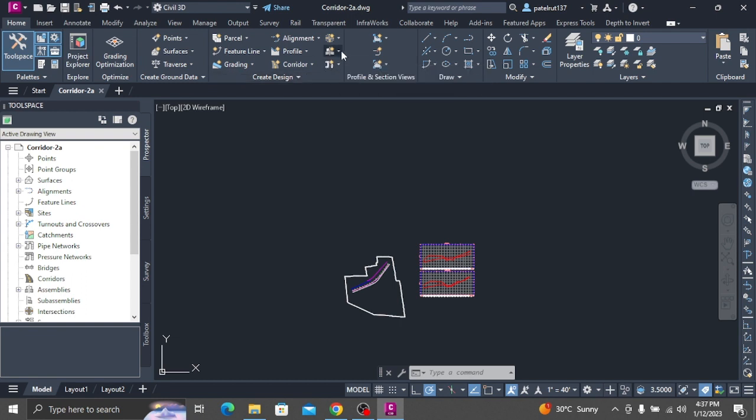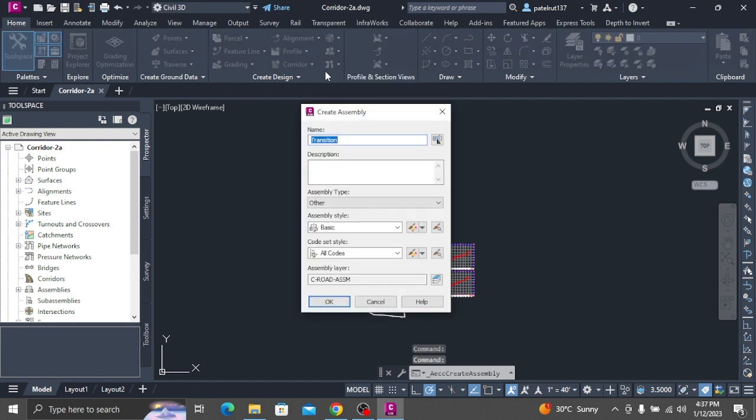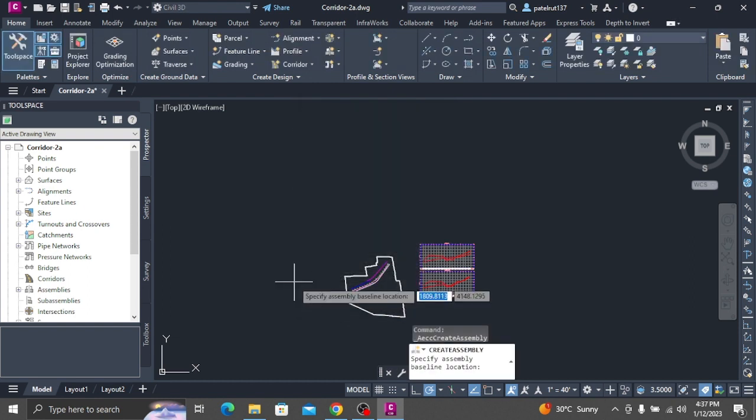Side, right. Default width, 14.0000. Depth, 1.0000. Transition, change offset and elevation. In the drawing, click the marker point on the assembly baseline. A lane is drawn, extending 14 feet to the right, with a slope of -2% and a depth of 1 foot. Add a curb and gutter subassembly.